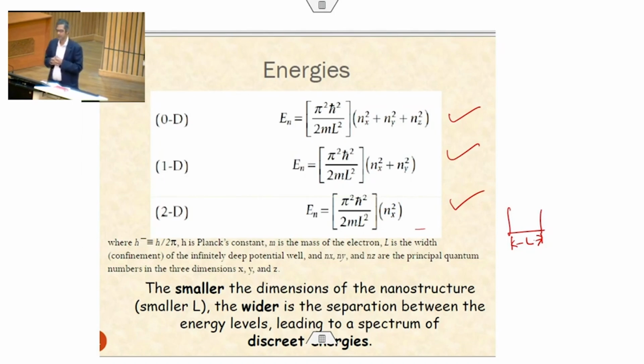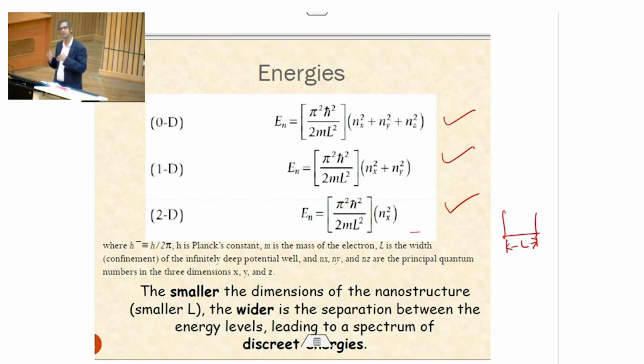Okay, what happens in 1-dimensional nanomaterials, which is very interesting. 1-dimensional nanomaterials have 2 dimensions in the nanometric domain and 1 dimension in the micrometer domain. So, they can act like a phonon waveguide, similar to optical waveguides for light. For example, if you take carbon nanotubes, several investigations show a carbon nanotube has a very high thermal conductivity along the length of the tube. That means the phonons are moving very fast along the length of the tube, just like in a waveguide.